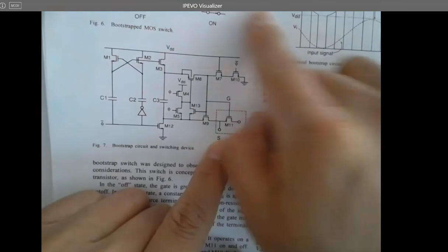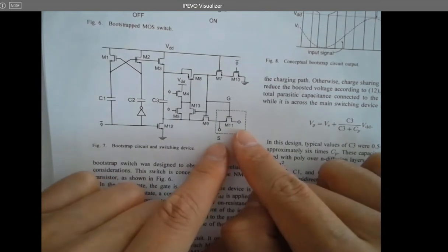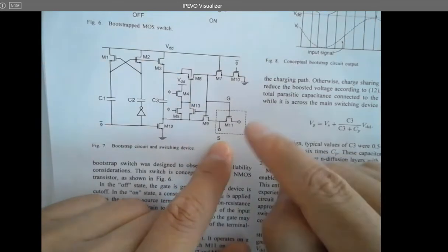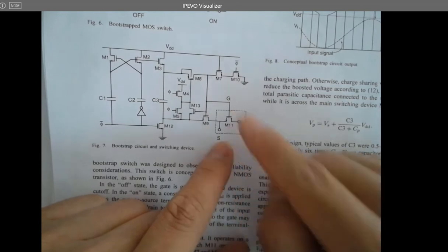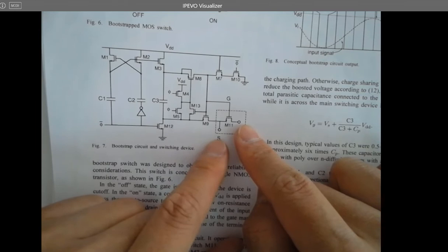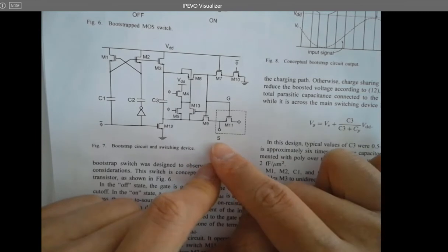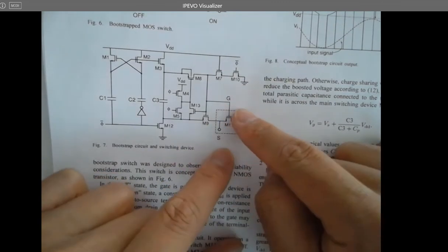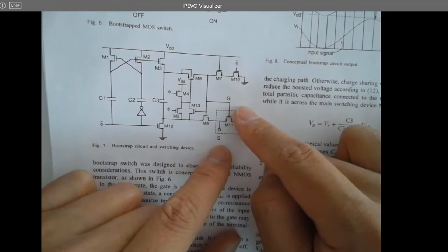And you're looking at the entire circuit, but this is only the pass gate. It's being used for this purpose, you know. So all the other parts are just serving the purpose, one, to increase the VGS to a higher voltage, so it is able to pass any signal, even including VDD. Whenever the signal is VDD, it is still able to pass VDD to here. That's the first purpose, all right? First purpose, pass all the signal levels from 0 to VDD to here. Second, to keep VGS consistent, or keep VGS to be a constant voltage. Why is that, right? We don't have to dive into that concept too deep, but just let you know.